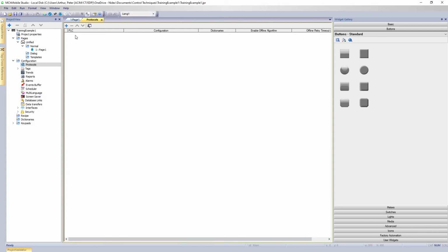So I'm going to, and of course we're a PLC, so I'm going to click Add Protocol. Here you get this little drop-down box here. So I drop down. Here are the supported protocols. Right? So you'll notice we support Ethernet IP as well. That's kind of a different panel that we sold at one point supported this, so we had to include Ethernet IP for those people who were upgrading. So here's the protocol we want to use. Control Techniques Modbus TCP. So I will choose that.